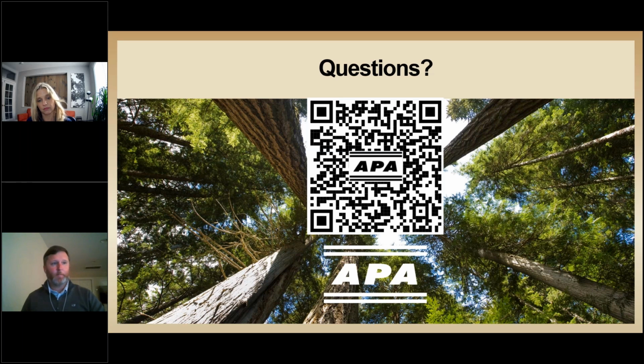Yeah, they probably came in before we finished covering that section. It's pretty basic. It's because these treatments are proprietary. They're not all the same. While we did perform testing, which showed about a 50% strength reduction, that was only on one particular product. So there are two key takeaways. One is you're likely going to have a strength reduction, but to find out exactly what that is, you need to consult with the actual treatment manufacturer. Yeah, I think that's good to reiterate. Doesn't hurt to say that multiple times.